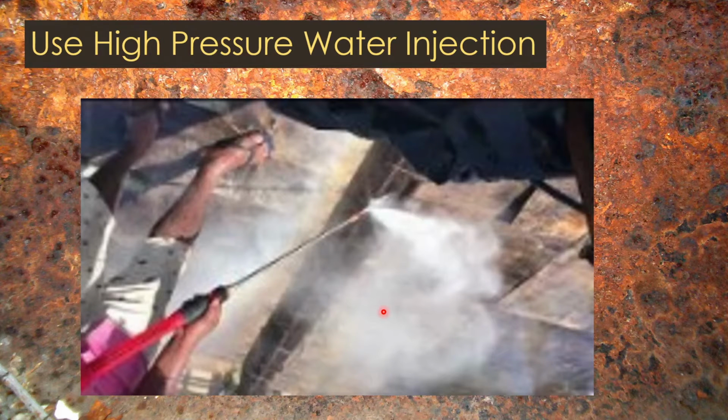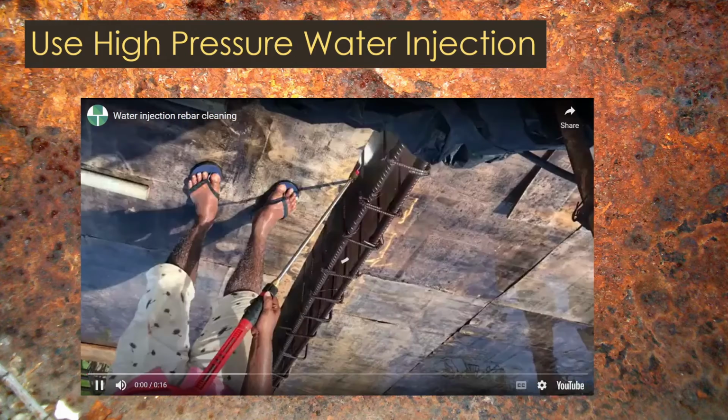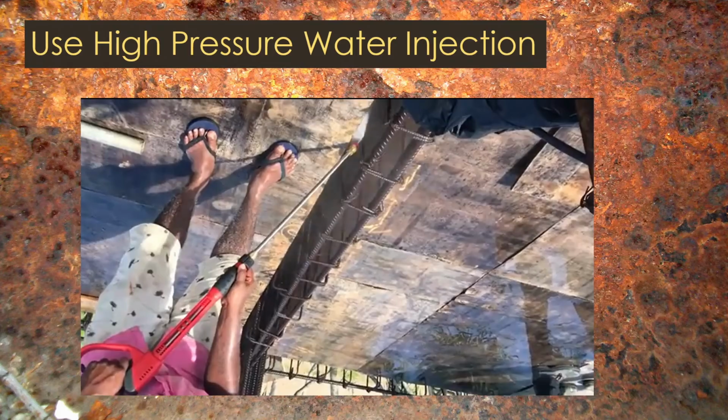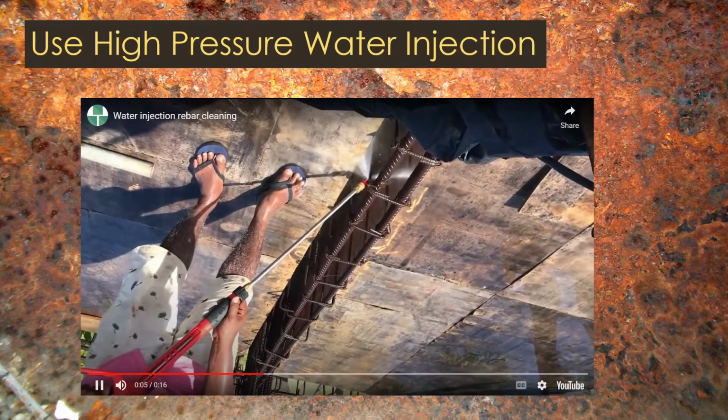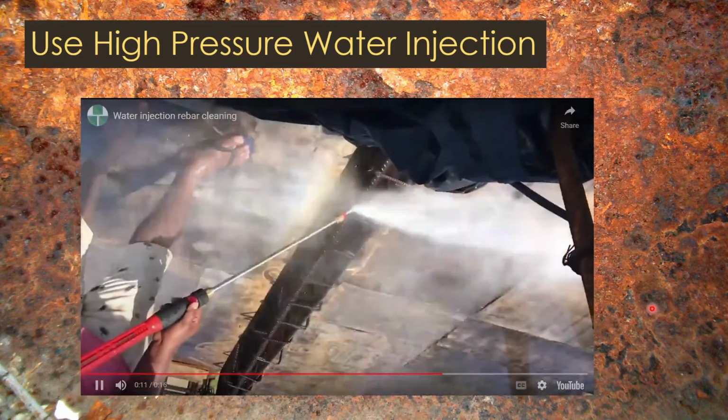High pressure water injection is also one of the common methods used to remove rust. This can be used for any metal, or for reinforcement cleaning. You can see here in this video the process of cleaning the rust from the rebar. This is a very simple thing. High pressure water is injected onto the rebar, and with that the rust is removed. It's cleaning and removing the rust from the rebar.